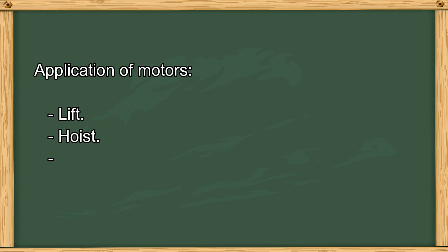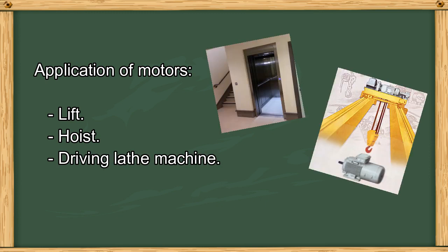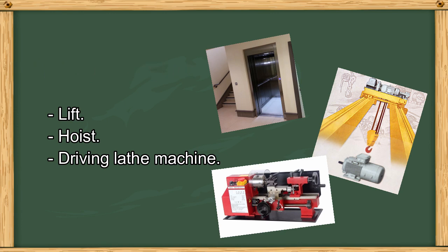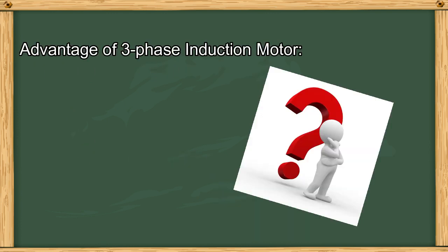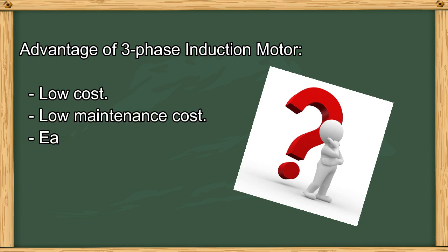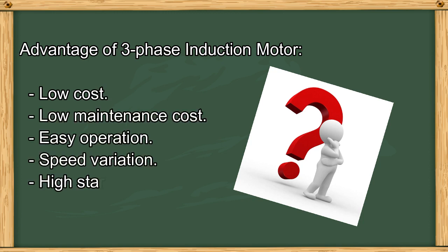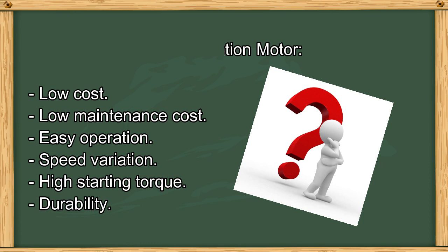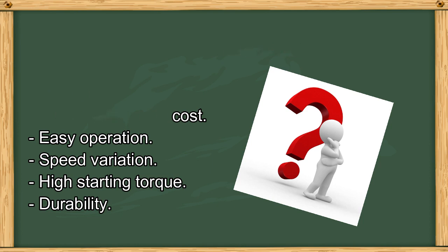Next, the three-phase induction motor can be seen used in lifts, hoists, drives and lathe machines. Alright, what are the advantages of the three-phase induction motor? Let's see. Firstly, it is low cost. Second is low maintenance cost. Third is easy to operate. Fourth is having speed variation. Fifth is having a high starting torque. And lastly, durability.